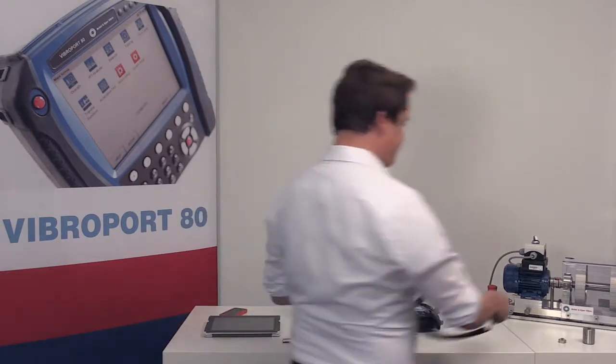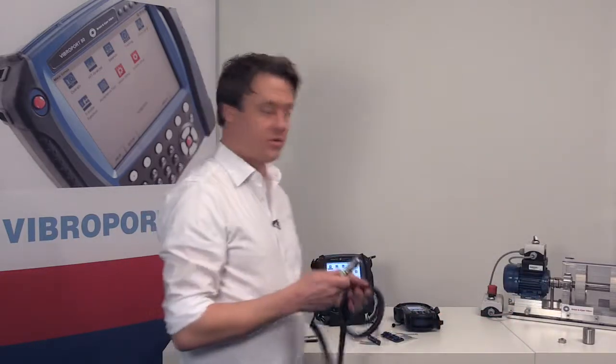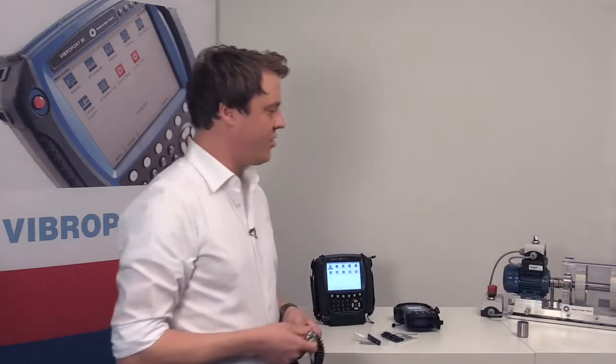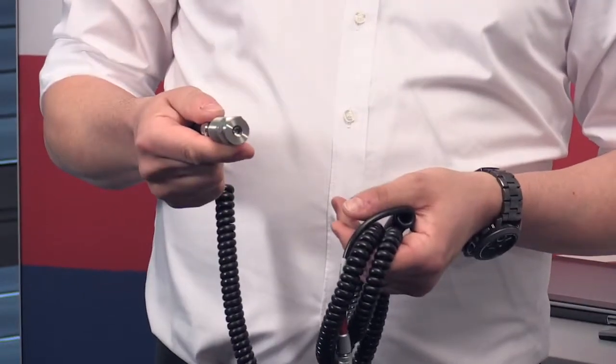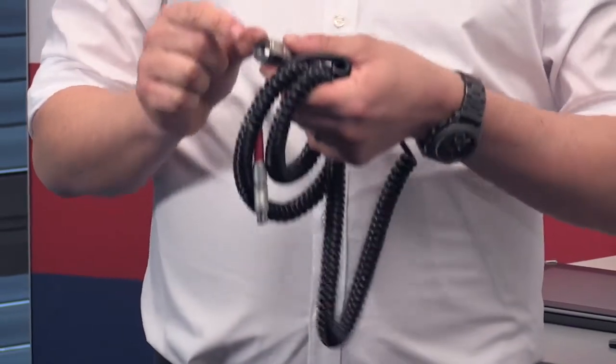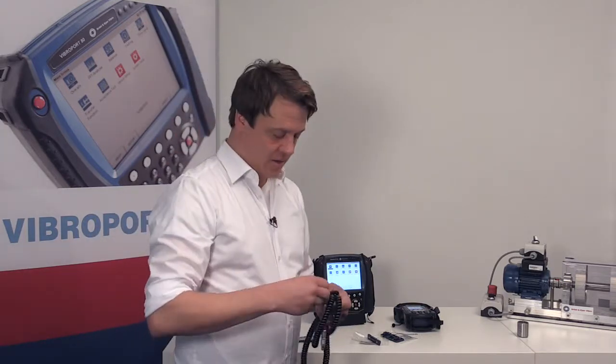Now I have the cable and the sensor. Can I attach it? No. What did I do wrong? Of course, you need a magnet. There are several possibilities to connect a vibration sensor. Ideally, you screw it on a place, because the stiffer a sensor is connected, the better the high frequency signals can be transferred to the instrument. However, of course, for convenient use, and in many cases, a magnet is the most appropriate thing you can use.